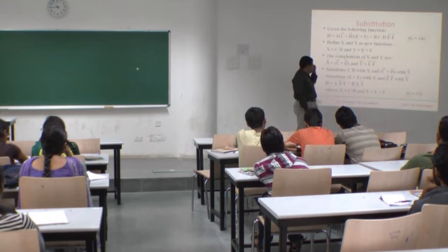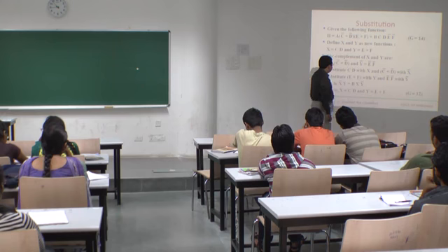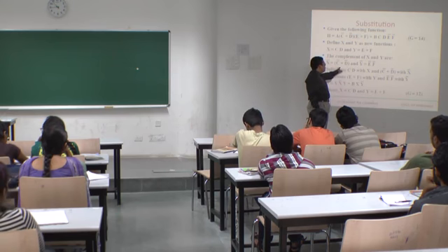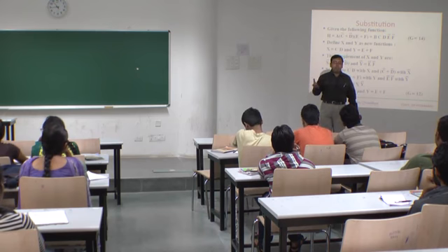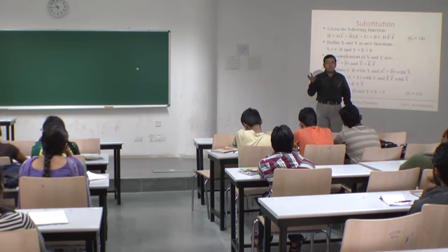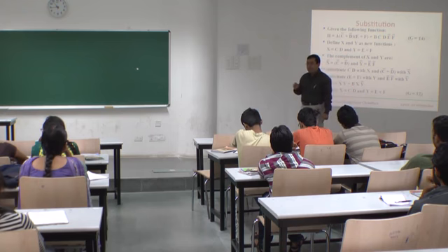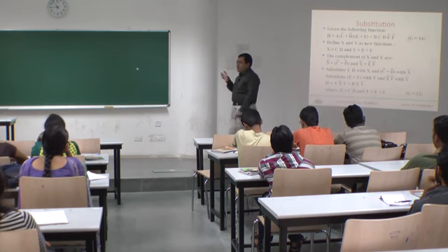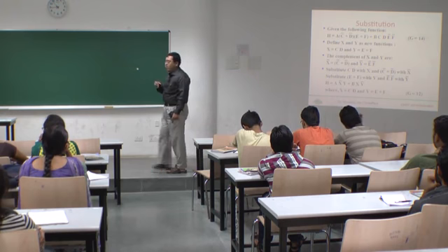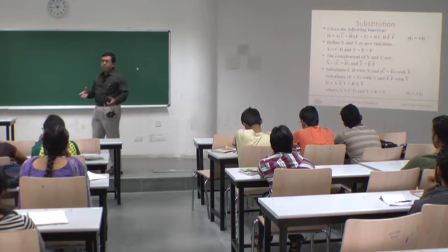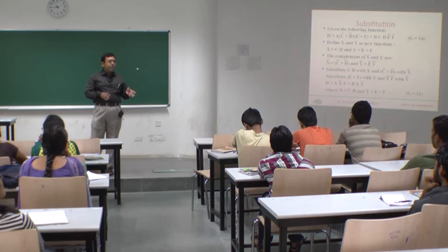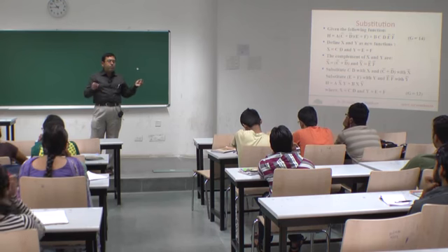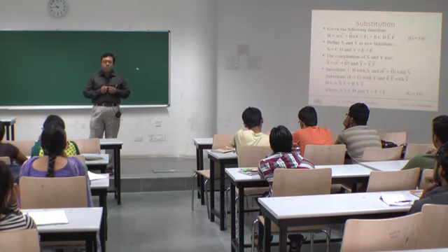Now, this is an approach where you see whether you are using some sub expression at multiple places or not. If you are using the same sub expression at multiple places, then you try to compute it separately and provide the output of that sub expression to the inputs at multiple places where you are using the sub expression.